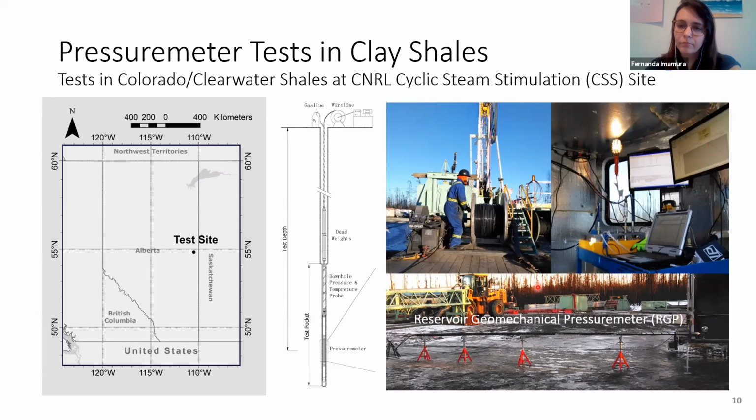So it can be interpreted with the well-established cavity expansion theories and can be compared with structural testing data along its stress path. I'm not sure if I answered your question, but I think the major advantage of Pressuremeter testing is that it provides a full stress path for the materials under the stress condition. Okay, thank you.